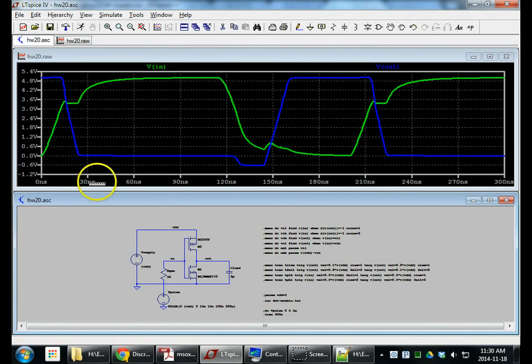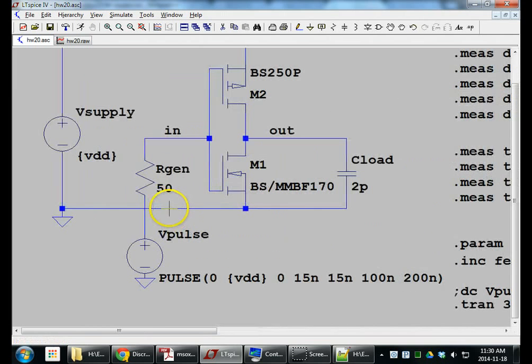So when the input goes up, this is V in. It's not a beautiful square wave anymore because we're on the other side of the resistor. You see that? So this is the square wave node here. But if there's any current flowing into this gate, which there is, we're charging up capacitors, you get a voltage drop across our generator resistance.